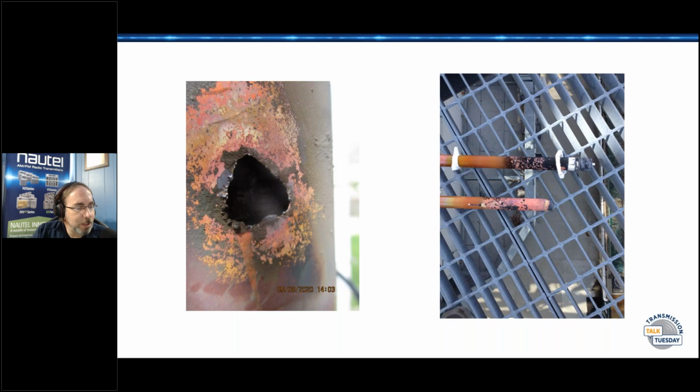Mike Fertini makes a good note about cleaning the flies and dust out of smoke detectors to avoid alarms and HVAC lockouts. And that is a really good point, one of those things that are easy to miss that we don't think about. Cleaning out the smoke detectors, and same deal with the batteries. Even if you've got an AC powered smoke detector, I'd hope it's battery backed up so that it can trigger an alarm if the power's out.